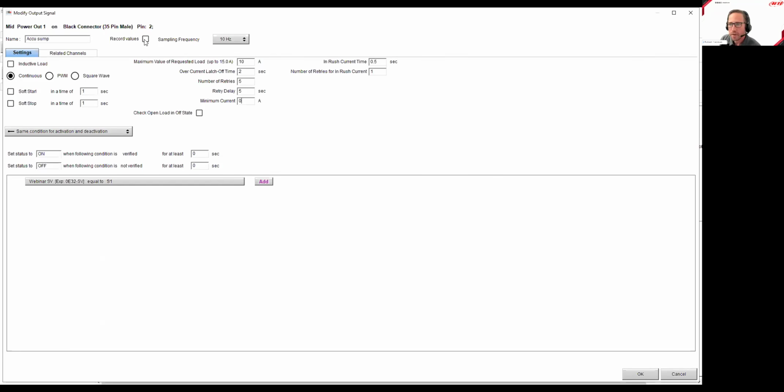I record heavy consumers and things that are critical to running the vehicle. So I like to see, the more data you record, the longer it takes to download. It just increases some of the time it takes to decompile and decompress after a race event. So rock lights, they either work or they didn't, and it's not going to be a huge concern if I don't need to pinpoint the exact time when a rock light failed. No huge added value by knowing that as being recorded, but a low oil pressure situation, you do want to know exactly when that happened.